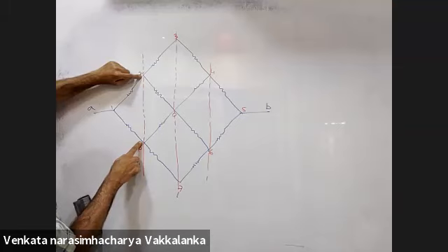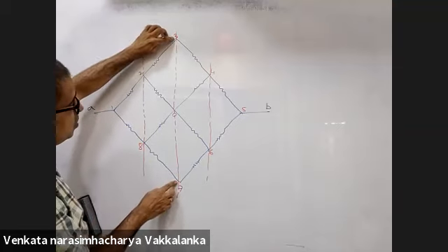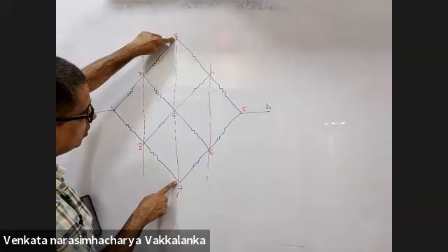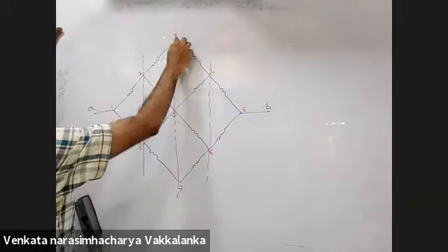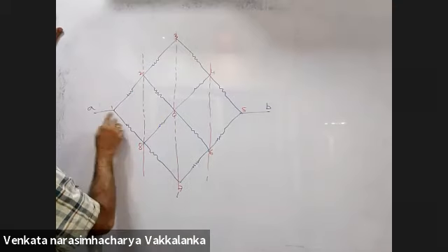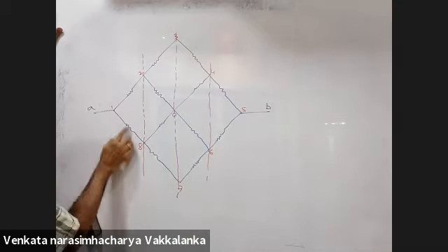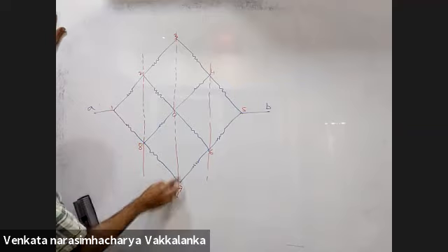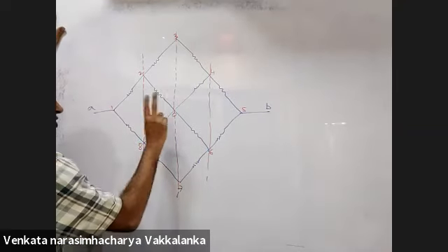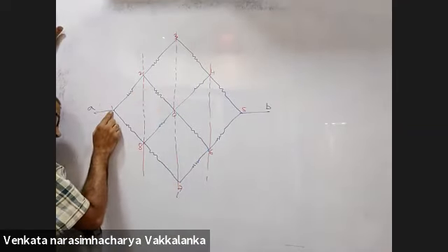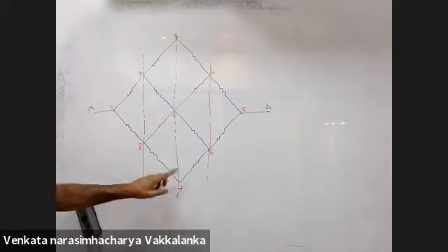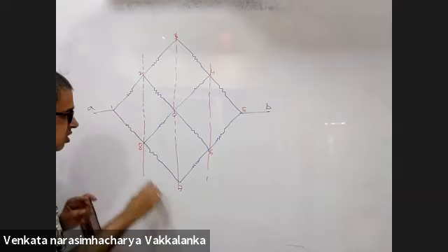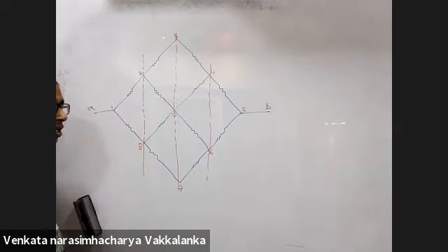After crossing two resistances each, both the points are equipotential. So two resistances from here, 1, 2, or 1, 2, or 1, 2. So all points which are at a distance of two resistances from 1 will be equipotential. Same applies for 4 and 6.